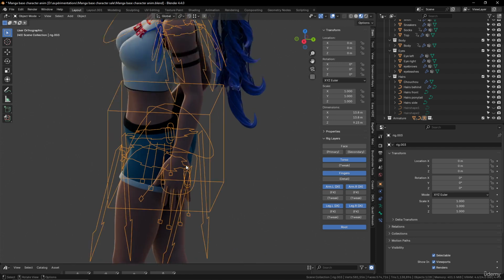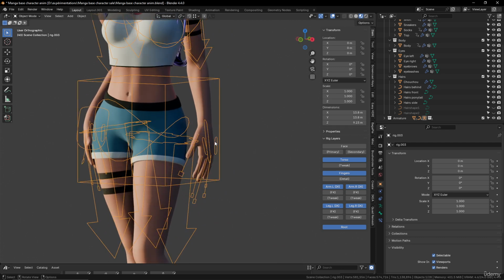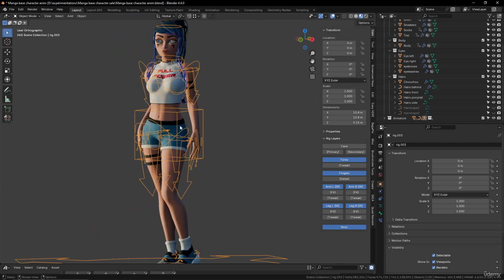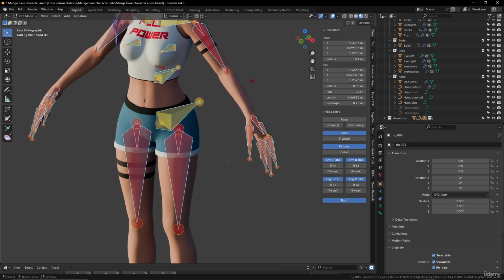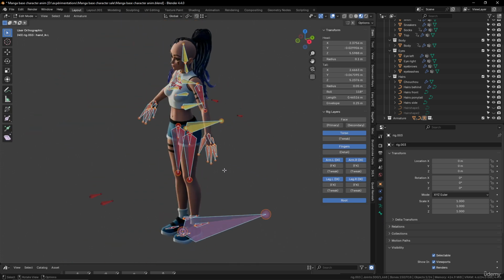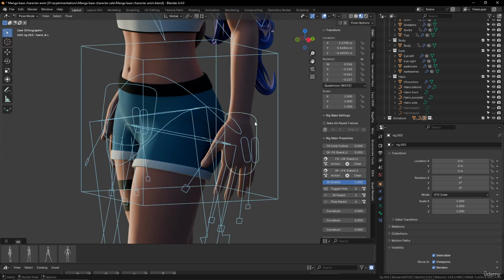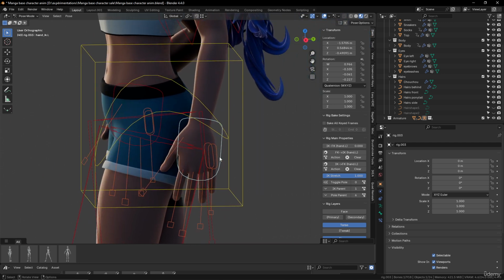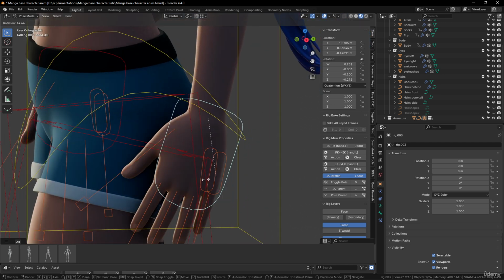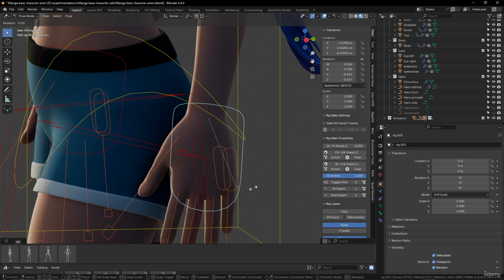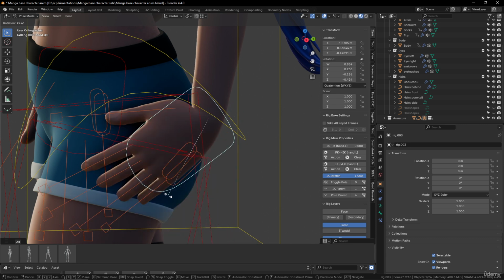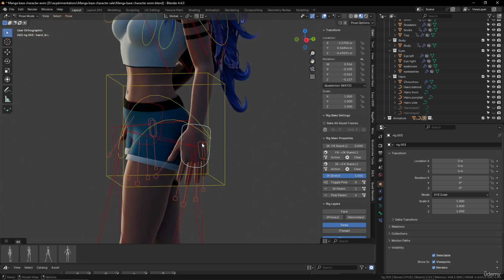Anyway, here is just an organic model, and you can see that here I have specific shapes, but this is the rig, okay? This is the rig inside the edit mode, where you can see the real shape of the rig over there. But if I go into pose mode and make a rotation of this, for example, you can see that I will have deformation of the bone, of the character itself, okay? Just like this. You can see this deformation over there. So this is the way of parenting an organic model, okay?